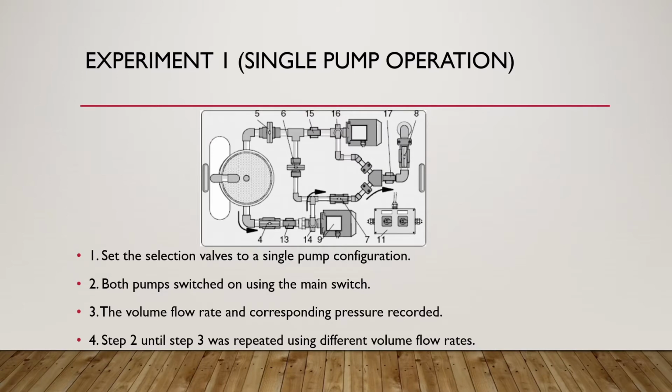Step 2, both pumps will be switched on using the main switch. The third step, the volume flow rate and corresponding pressure will be recorded. And the final step is that step 2 and step 3 will be repeated using a different volume flow rate.